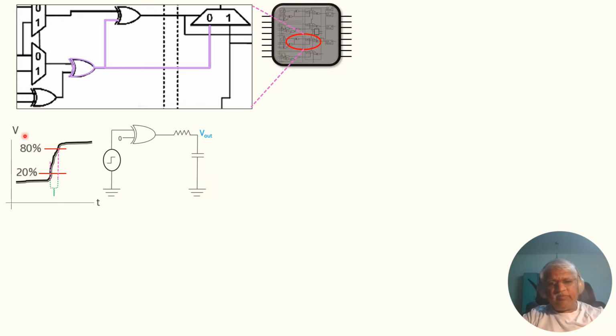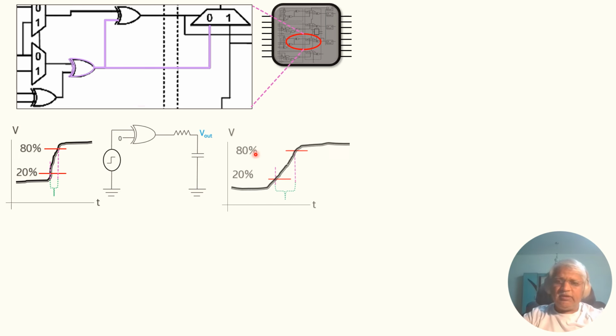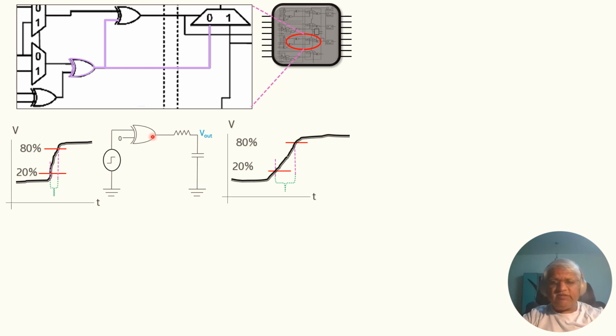So if this is the input transition time, then what will be the resulting output transition time of this cell with this load? What we will be checking is, we will be considering the input transition and the output load of this cell, and then we will figure out what is the output transition of this cell. For this purpose, we will use the dot-lib view to estimate